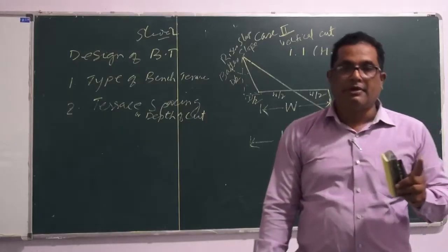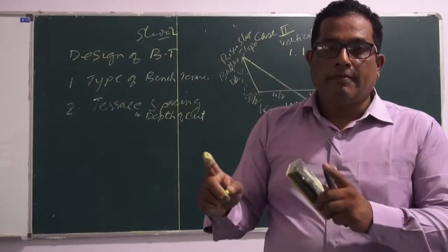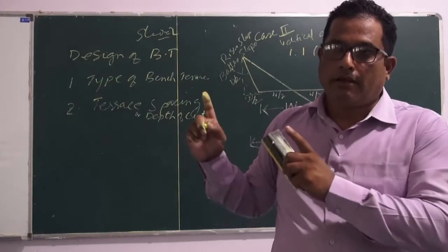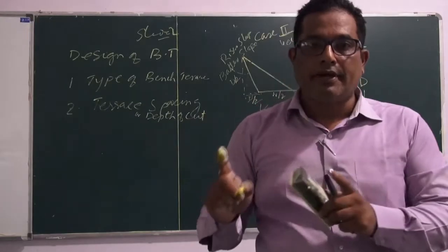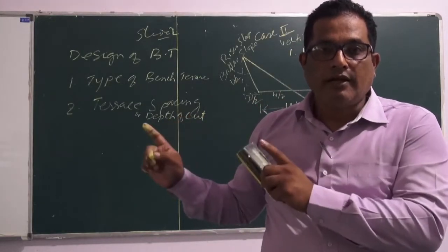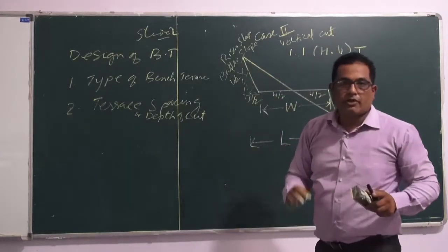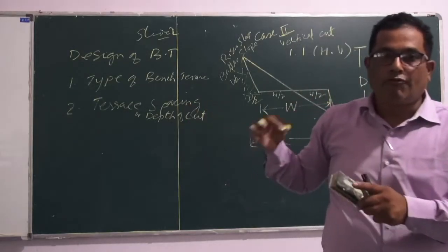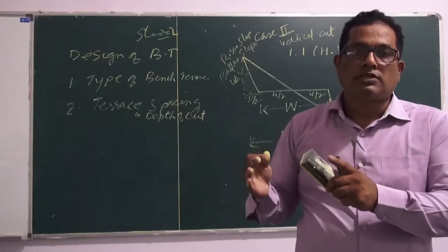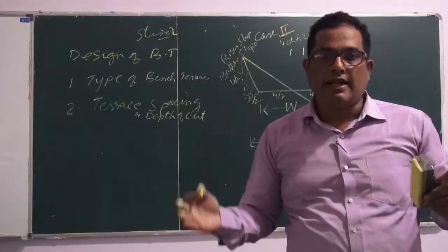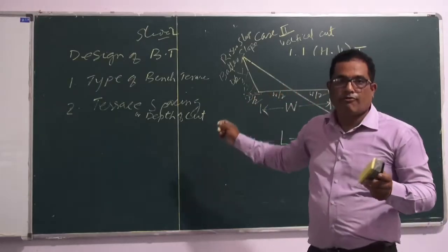One thing that you have to remember is that this vertical cut, although it won't be stable, has less area lost due to bench terraces compared to having a 1:2 or 1:1 batter slope. Because with the 1:1 batter slope, this area we cannot cultivate, and over a coverage of 1 hectare, almost 20% of the land surface area will be lost because of the construction of bench terraces.